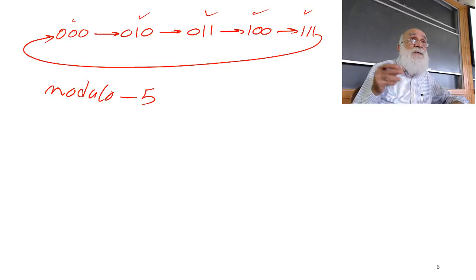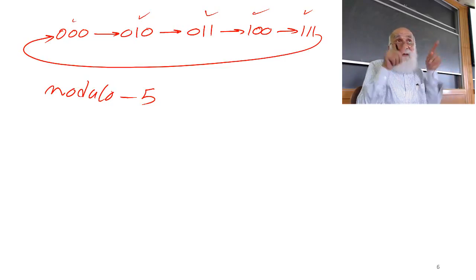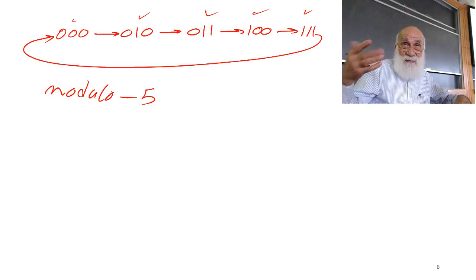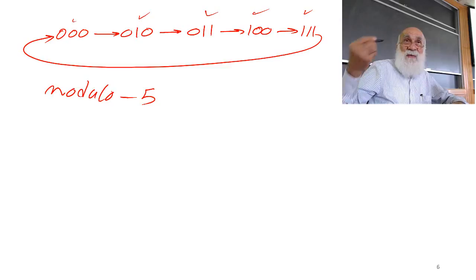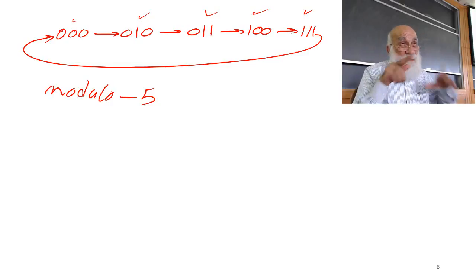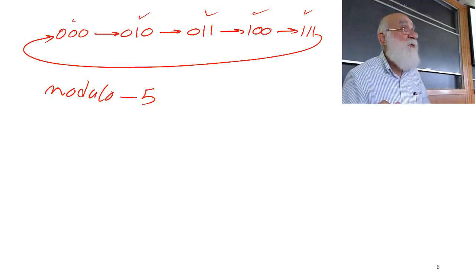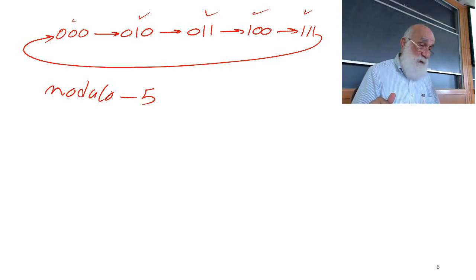And these counters, unfortunately, we cannot trace the inputs like what we did yesterday, which is going through the pattern, finding two ones, adding them together, and using them for the next bit. That's because it's not binary. If it is a gray code counter, we can do XORs and then do something similar to what we did yesterday also.